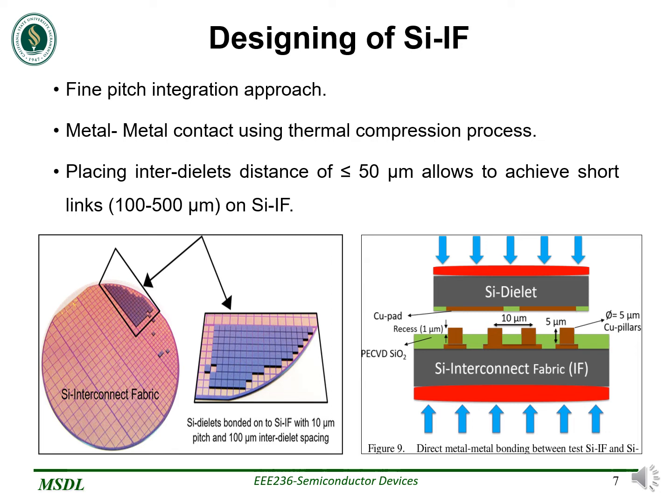This technology provides better chip package interaction, elimination of under bump metallurgy, and decrease in fabrication cost. We demonstrated the continuity of 10 micrometer pitch interconnects with inter-die spacing of 100 micrometers and alignment accuracy of less than 2 micrometers.